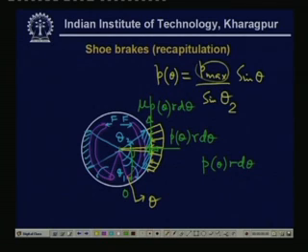which is the perpendicular distance, and if you consider this length to be, let us say, a, then this is nothing but a sin theta, as you can verify, because this angle is theta. So, this is a sin theta, and this is the moment of this force P theta r d theta, and we will have to integrate from theta 1 to theta 2. This gives the moment M1.